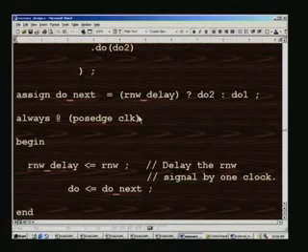And here what we do is we want to have a pipeline stage, we want to register basically. So that we do only at always positive edge clock, and here the final output is DO, and the DO is derived from basically a DO next. This in turn is derived from either RAM 1 data output or RAM 2 data output, and that depends upon this R and W control.